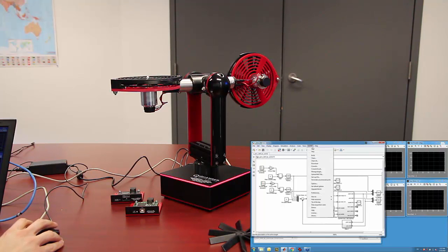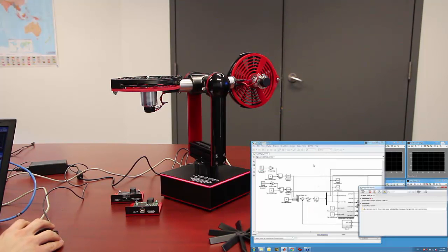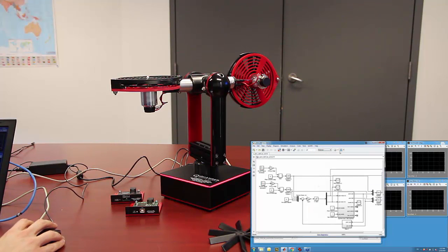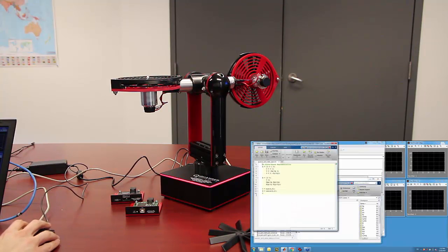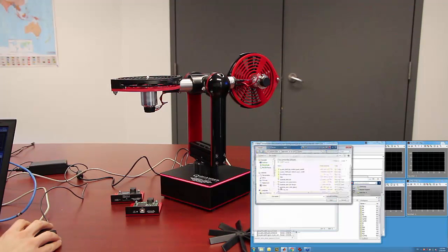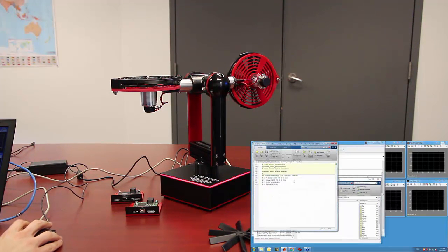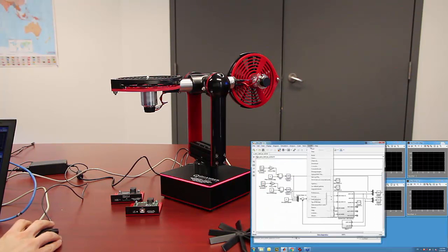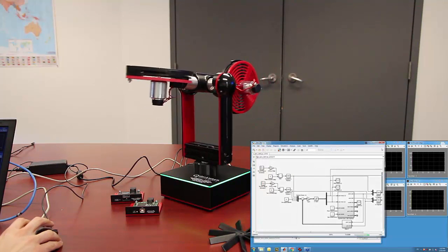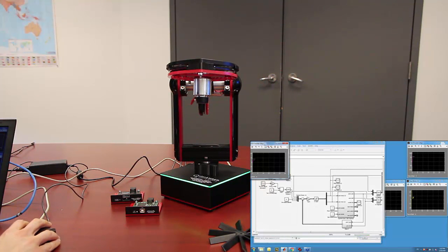So now if I run this, using the same set point, so if pitch and yaw set point are the same, I'm just going to go ahead and build this. To give you an example of what we supply, some of the files, here's a state space model that we have, and then here is the LQR controller. I'd run this and it generates my gain, and then I can go back to this and go Quarc start to run the controller. And now let's see the difference in here.